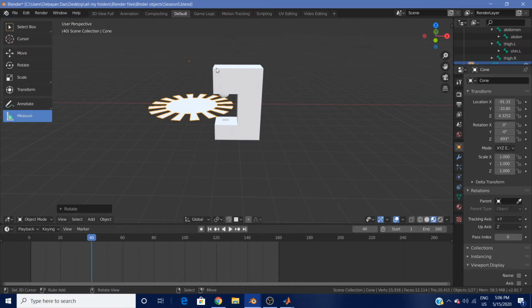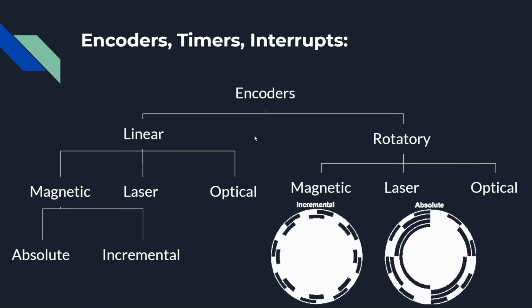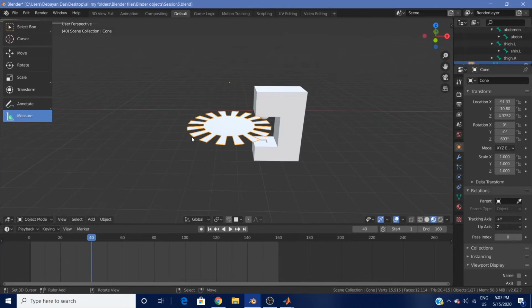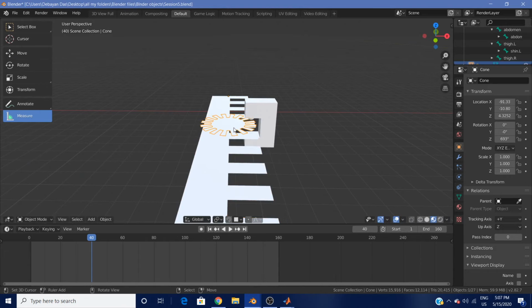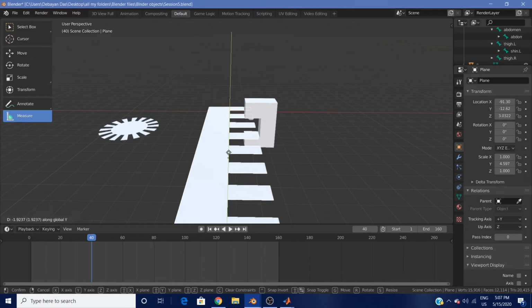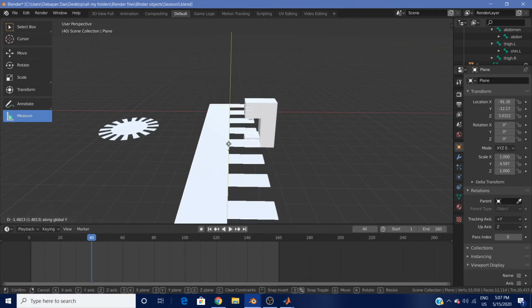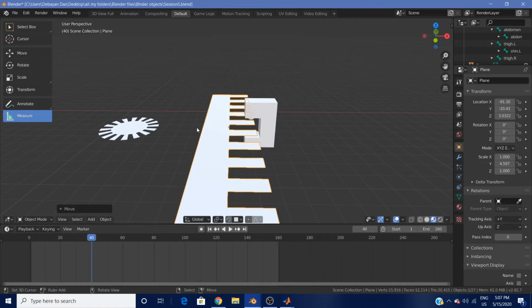We can't do that just by measuring the voltage, because even two identical DC motors would have slightly different speeds for a given voltage, because they're very, very sensitive devices. So we really need to know what it practically is, and we really need a controller to take care of it. Now, in case it's a linear encoder, this particular thing would be placed right here. This one would move out really fast like this, and we would be able to tell at what speed the joint is moving.